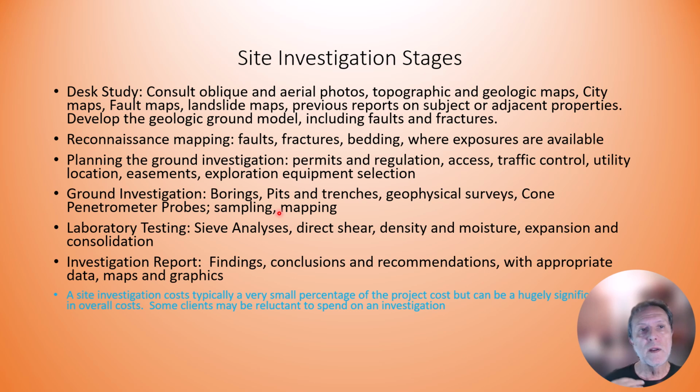Once that's done, 1 day, 2 days, 3 days, a week, whatever it may take, we get the samples and we take them back to the laboratory to do laboratory tests. Sieve analysis for texture, direct shear for strength, natural density and moisture. Is it very wet? Is it very dry? Expansion properties, especially for plastic clays. If they get wet, they can expand and compromise foundations and utilities, roadways, etc. Consolidation, are these underlying sediments so soft that if you put a load on them, they may sink? So that's something to look for.